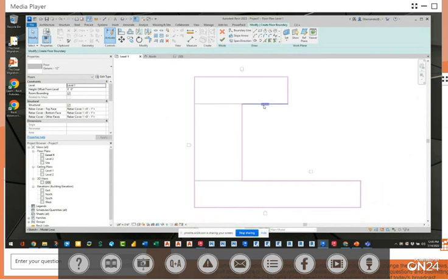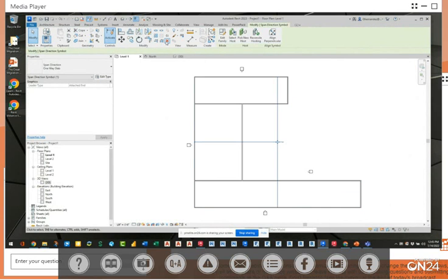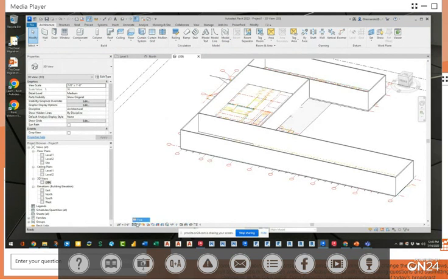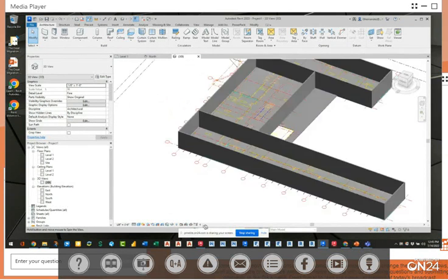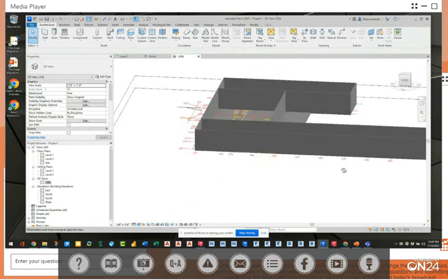And these double lines are basically telling me the direction, or the span direction, of the structure. So maybe I would do these in 3 different slabs and have my structure going left to right here, top to bottom here and here, whatever. I'm just going to keep this in one. Now I finish it out, and it'll throw in this span direction symbol. But now if I go back to my 3D view, right, now I've got my project started there. I've got my floor. I can start building this.